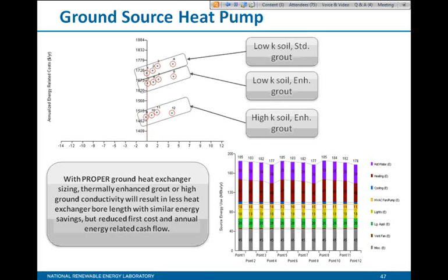Is the model smart enough to pick up on that, or is that just practical? So in BEopt, if a user chooses to hard size every parameter on the ground heat exchanger, he can run a 1-year simulation. However, a warning message will show that it is at the user's own discretion, that there's a high potential the system is undersized and that 1 year's simulation results do not really represent a steady state.